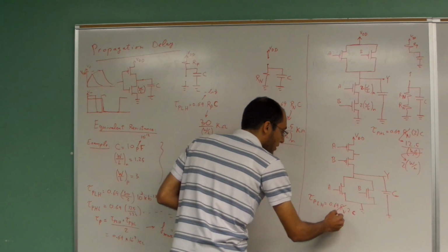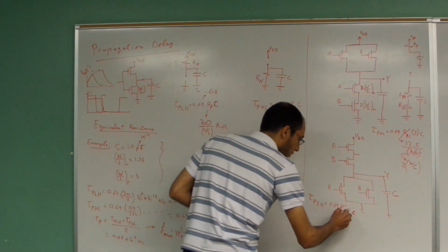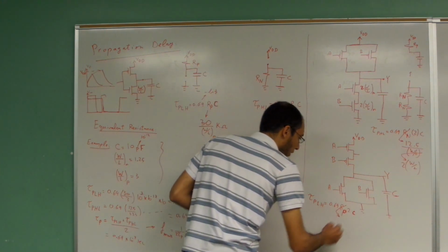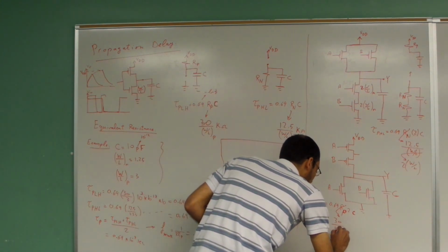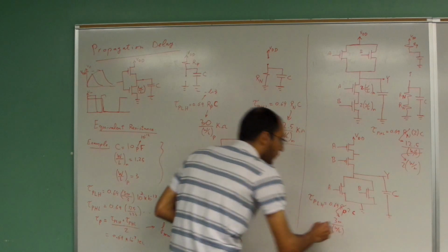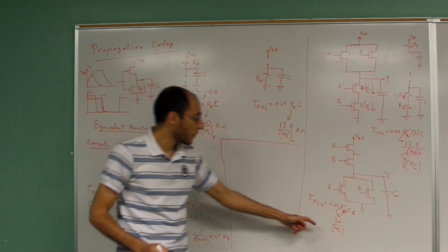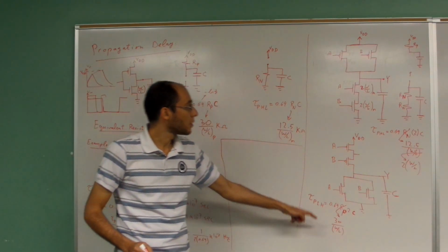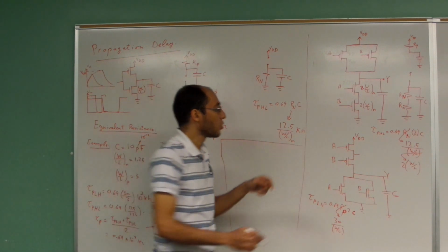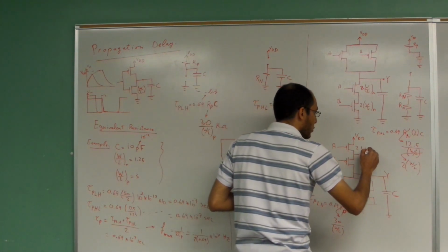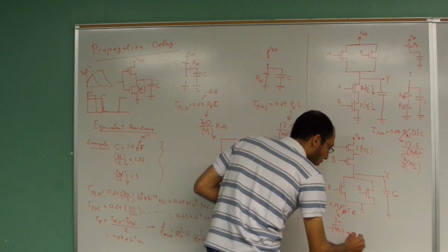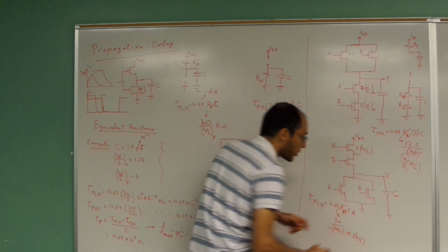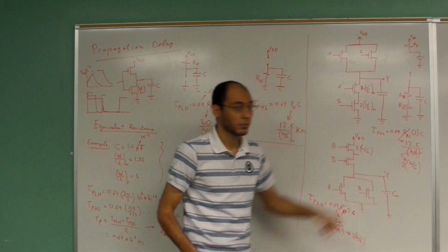So, what is the value of Rn? Oh, that's Rp. Okay, what is the value of Rp? It's 30 over W over L, whatever the W over L is. If the W over L was designed to be twice as much, then in that case you substitute this by 2 W over L, pretty much as we did here, right?